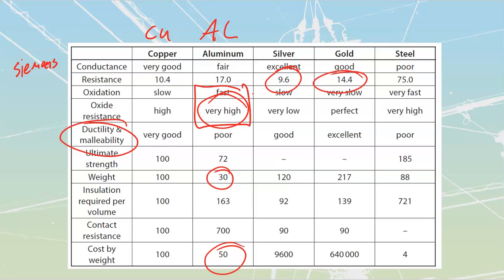Last one that we have heard about before as well is cold flow. Cold flow is just the fact that aluminum reacts to being under pressure by equalizing. Remember how nature tends to want to go in balance? Aluminum tends to self-balance quite easily. If we place it underneath pressure, underneath a lug, it will go and flow out from underneath there to go and reduce that pressure.